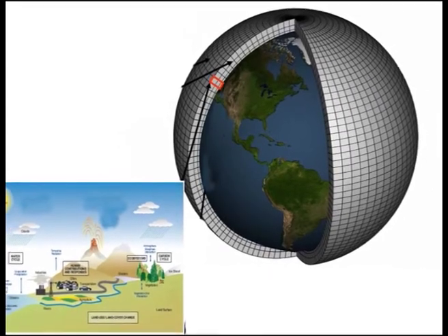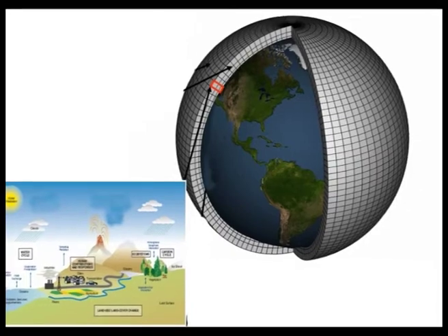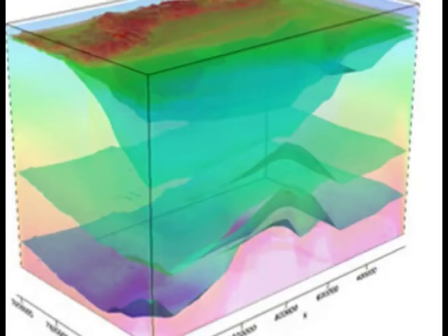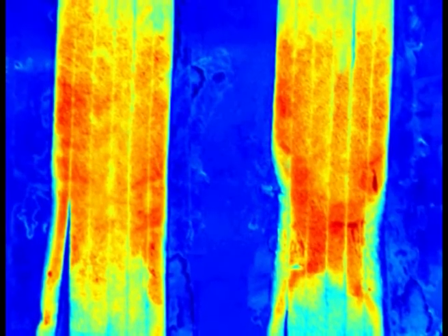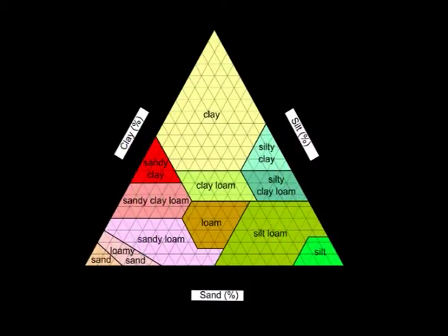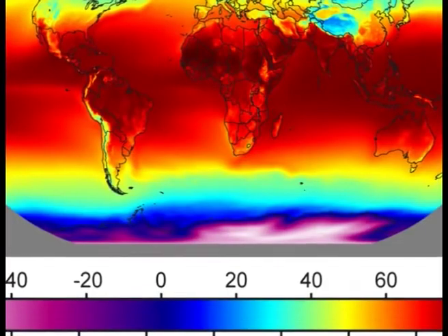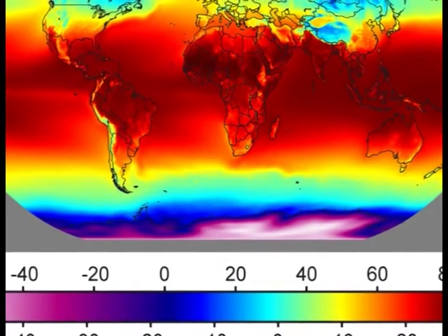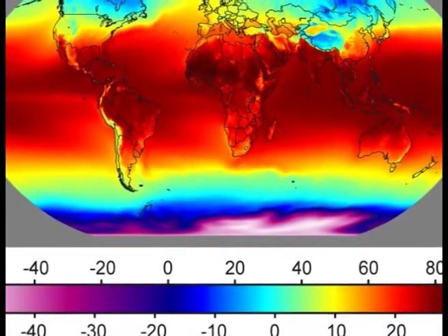However, they are generally relatively thin and are not found too frequently. If present, marine shale makes excellent geological markers. Gamma ray logs have been used to distinguish some uranium producing horizons in sedimentary rocks from the western United States. In more recent years, gamma ray logging has been used to distinguish different freshwater aquifers separated by clay shale in alluvial aquifers in sedimentary bedrock, confined artesian type aquifers. The drop in the gamma radiation shows the transition from clays to sand and gravels.